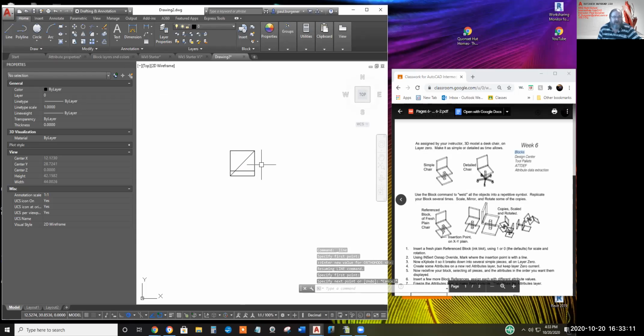However, something like a refrigerator, or a bathtub's a better example. Bathtub, you might put the insertion point at the corner so you can snap it into the corner of the bathroom in your floor plan. An oven or refrigerator, you might have midpoint in the back so you can snap it to a near point on the wall. Ceiling fans probably in the middle, so we'll just do middle today.